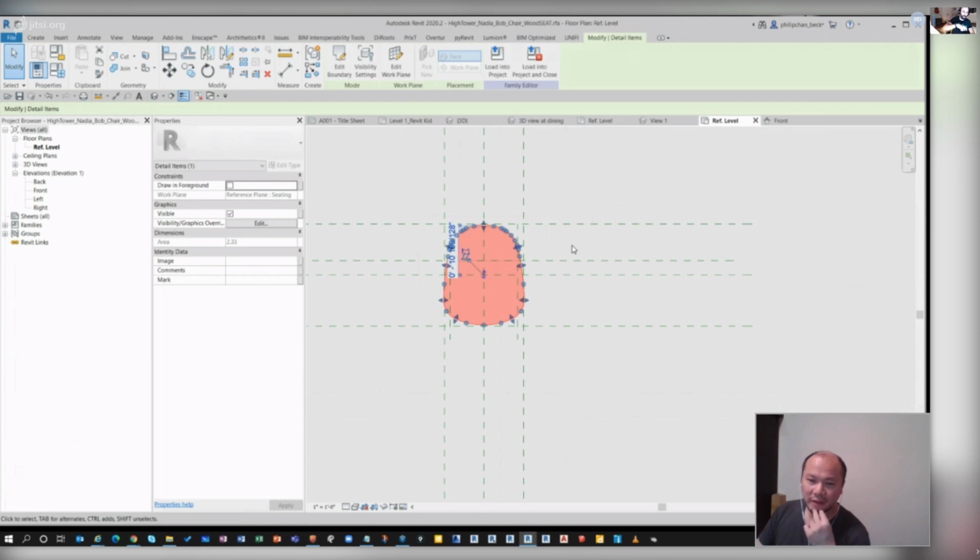Yeah, right? Because remember, you moved your chair down, -1.6, and it actually was under the table, because wherever Revit was defaulting that mask to, you can still get it underneath by telling Revit I want it to be lower, right? Yeah. Masking region is kind of tricky in the family editor environment.